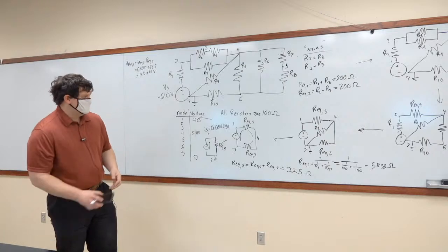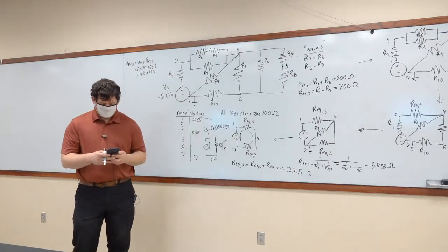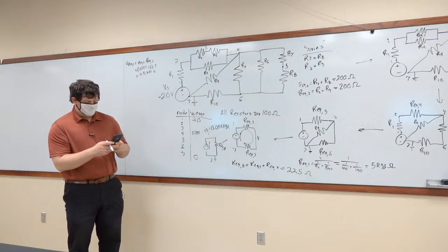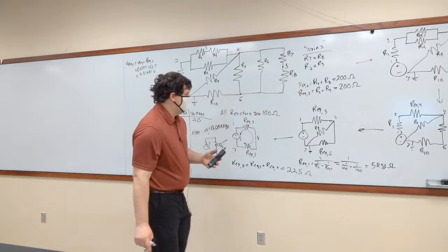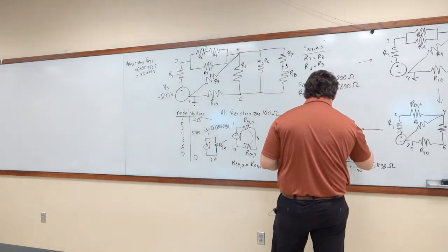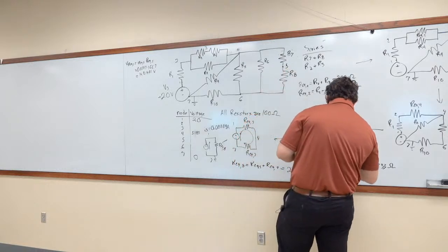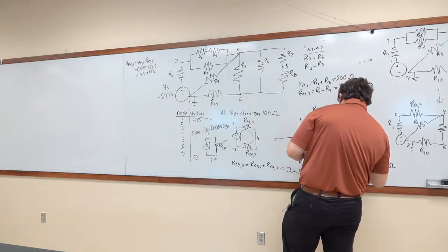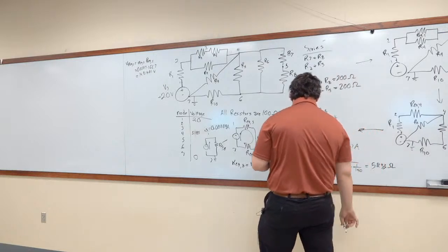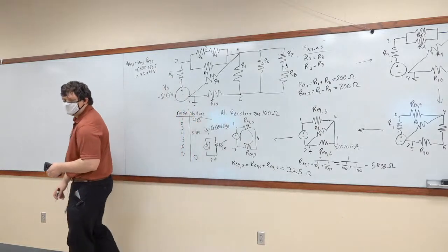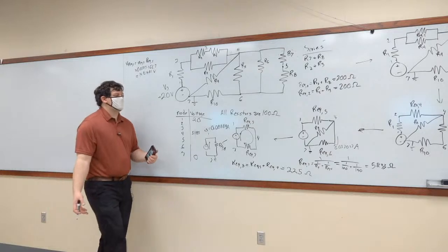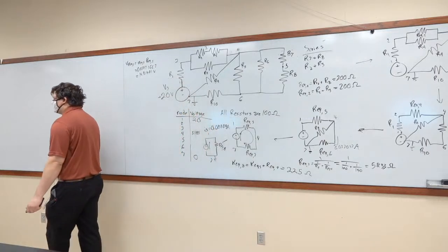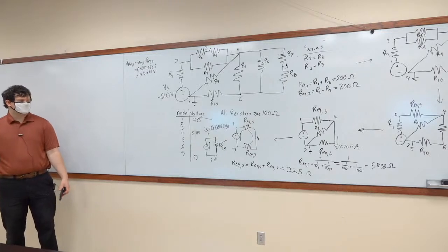Quick maths. With REQ6 being 140 ohms, 5.185 divided by 140 means that the current going from 4 to 7 through this branch is equal to 0.037 repeating amps. All right, which means that the rest of that 0.0888 repeating goes through R9. That's all that means. I don't want to calculate that because I don't care about R9. I'm just trying to find the node voltages.